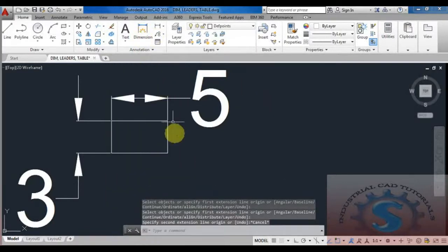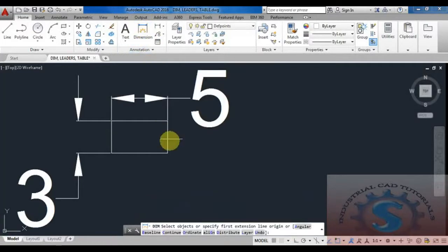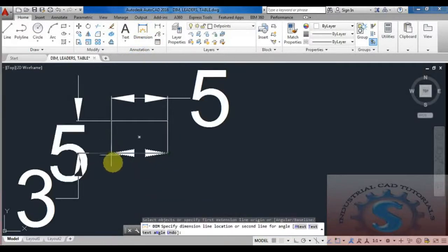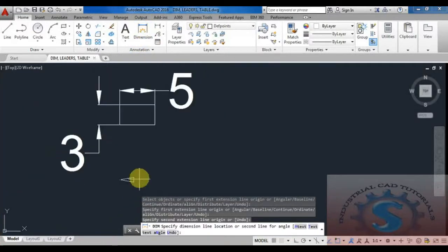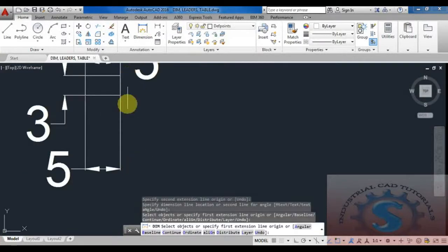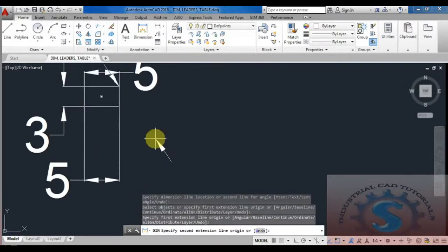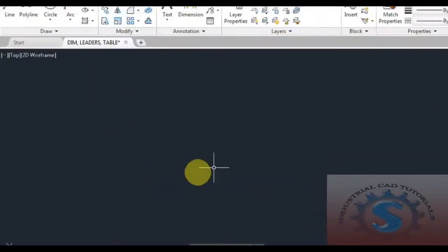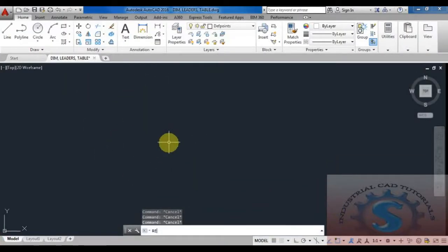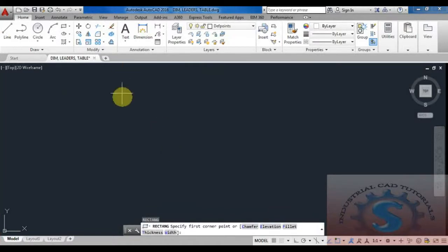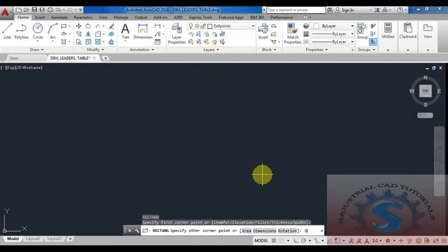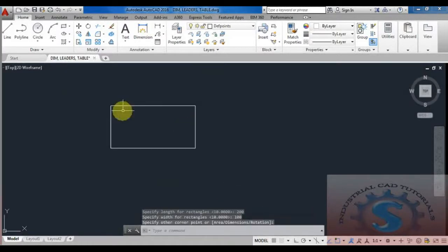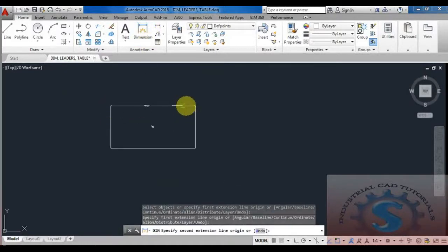After that I'm giving all of the dimensions to the rectangle, the 5 mm and the 3 mm like this. You can observe on the screen. I will show you. If you want to give a quick dimension, simply click on the dimension in the annotation. The quick dimensions will appear. See, I am specifying a rectangle of length 200 and width 100.